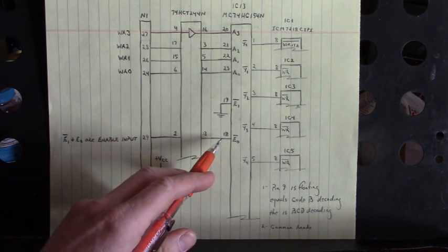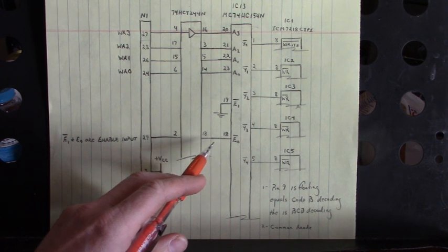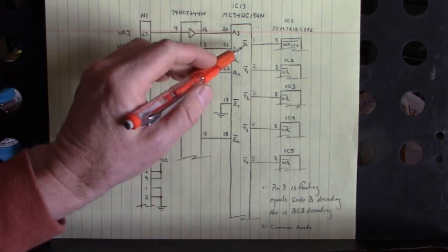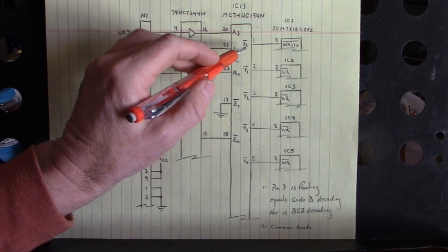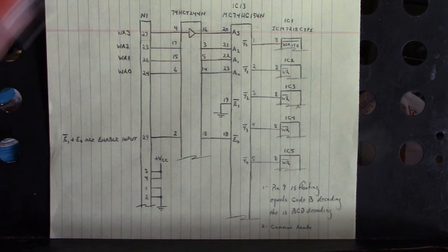When I place the input enable on 18 back to high, this output will go from low to high, thus writing that data to that selected 7-segment display based upon the input data and the digit address that we have already set up.